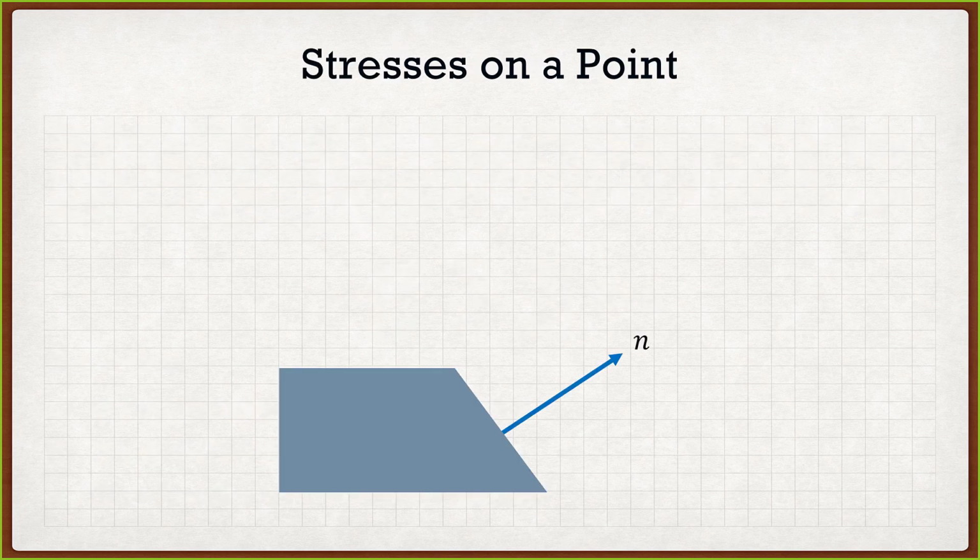Now, if we look at our equations, we're basically analyzing the stress at a point. If I were to make a cut in my object or my continuum, I have a normal vector n which is perpendicular to the cut, and it basically defines that cut. Also, when I cut, I expose the internal stresses, and we capture those using a traction vector Tn. To calculate Tn, it's just going to be sigma, our Cauchy stress tensor, multiplied by that normal vector n. The traditional formula is technically sigma transpose times n, but in this course, sigma, our Cauchy stress tensor, is always going to be symmetric. So you technically don't have to transpose it. If you do, great, but it's not really required.